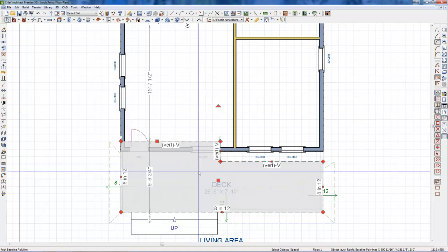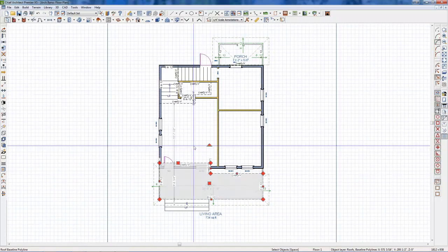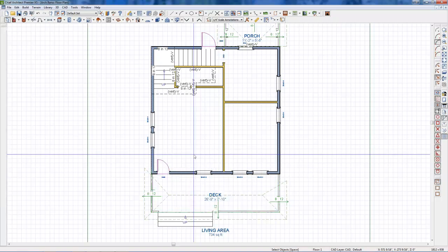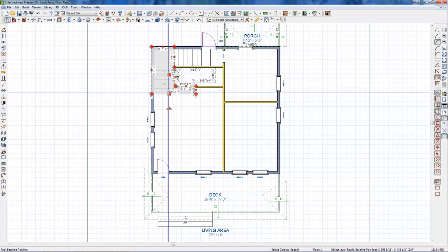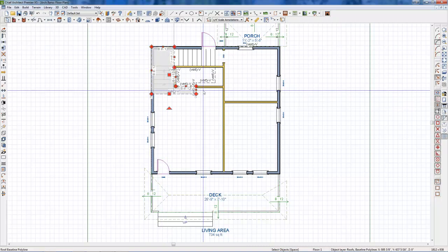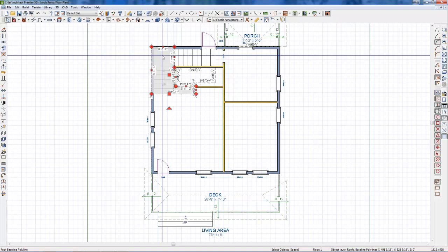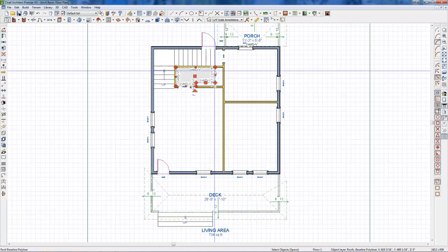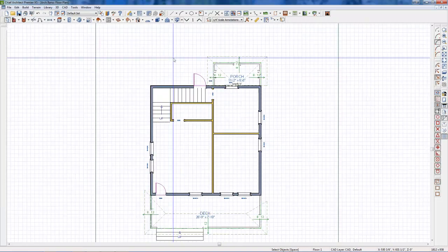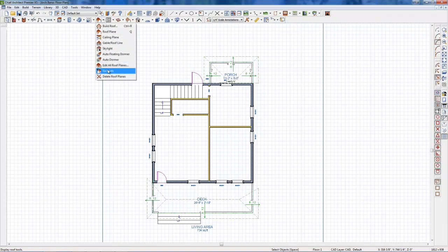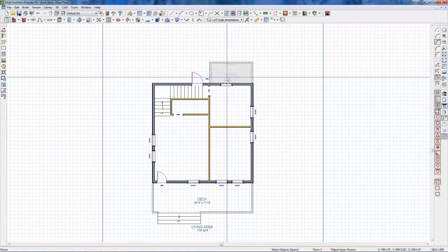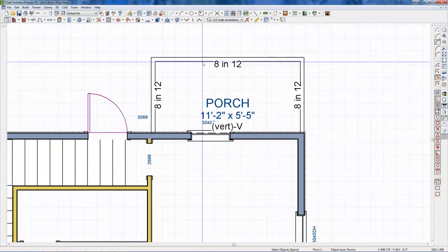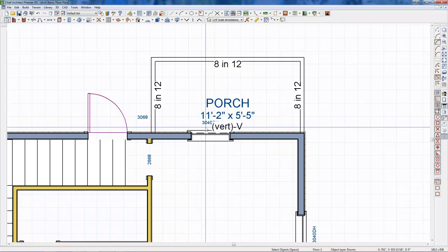Now, we don't necessarily need to use that in your case. So what I'd like to do is just delete the baseline polylines, because if we don't, then the computer will just continue to build a roof exactly over the baseline polylines. But we don't need it to build over those baseline polylines. We're going to build it ourselves. So I'm going to delete those, and I'm going to delete the actual roofs themselves, so they're gone. I'm just going to make sure I get all the baseline polylines out of here as well.